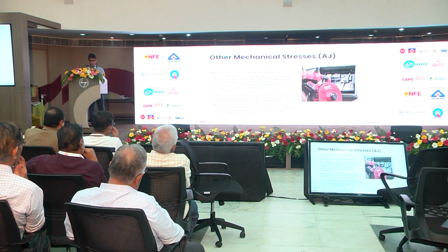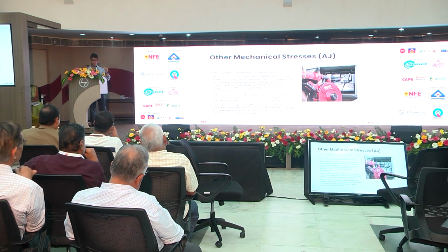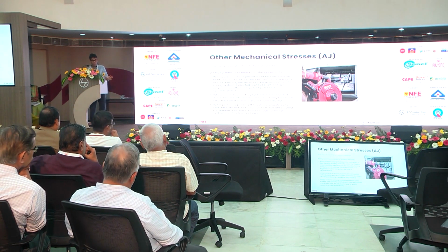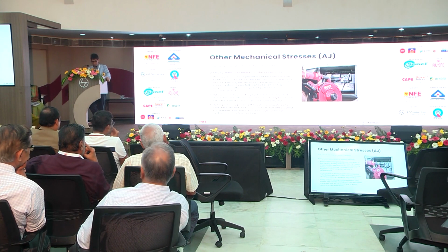Now, other mechanical stresses, there are more. So if you have a wiring system that penetrates a load-bearing element, such as a column or beam, firstly, you must make sure you can do that. So you must consult with a civil engineer or other competent person.